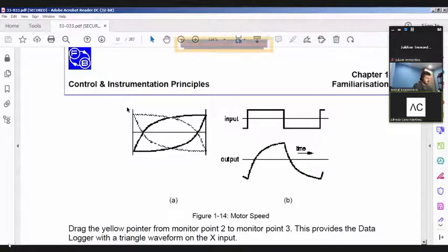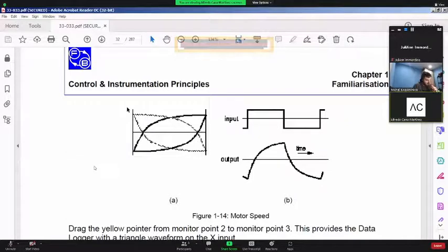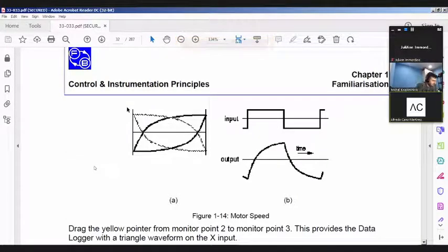Sometimes you care more about rising time. Sometimes you care more about settling time. So depending on the application, you may want to use one more than the other, right? Or emphasize one action more than the other. That is why when you max them out, you probably will not see any kind of perfect behavior, because you are actually pushing this thing in opposite directions, right? One of them will fix what the other is trying to make worse. You see what I'm saying here? Okay. You want to fine tune it to whatever application you want to have.